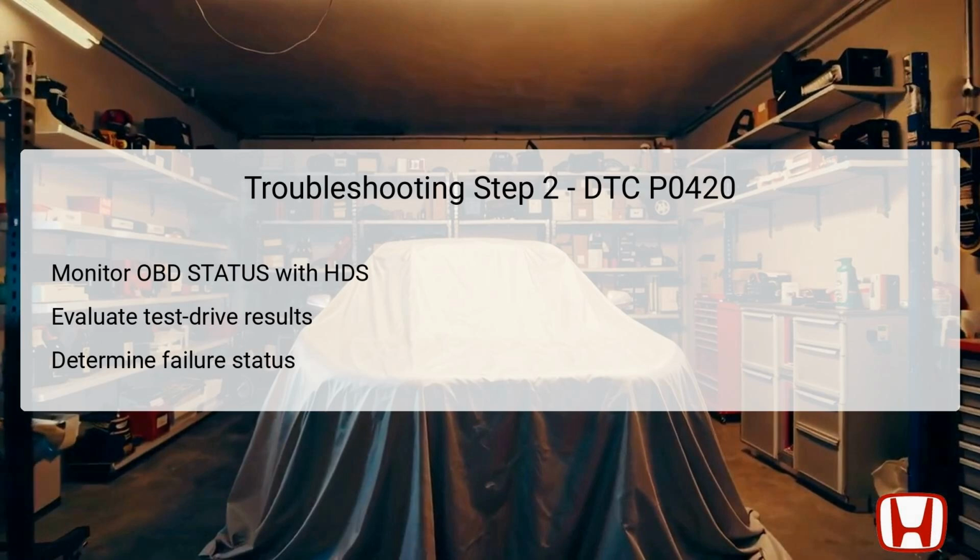For the second troubleshooting step, continue the test drive until a definitive result appears on the HDS. The ongoing monitoring of the onboard diagnostics, OBD, status for DTC P0420 is crucial during this phase to assess the performance of the catalytic system in real time.